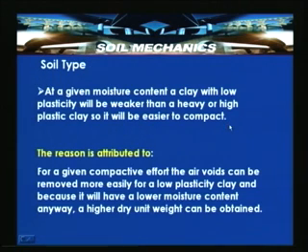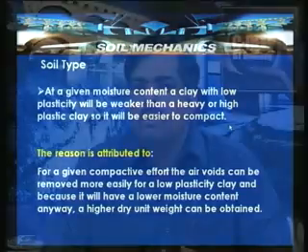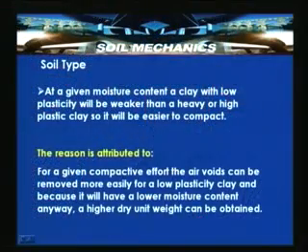So, we have seen in the previous slide that at a given moisture content, a clay with low plasticity will be weaker than a heavy or highly plastic clay. So, it will be easier to compact. Let us look at the reason why.